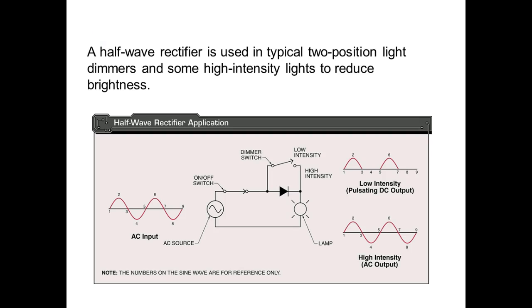So this is talking about a light. The light is going to see RMS, right? So if this was 120 volts RMS, and I close the switch, it's going to short out the diode. So now my AC flows around and goes through the load. So if this is 120 volts RMS, then the light bulb would light for 120 volts RMS.